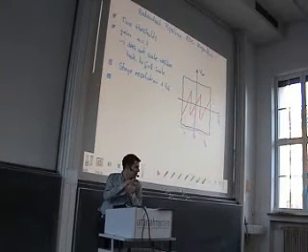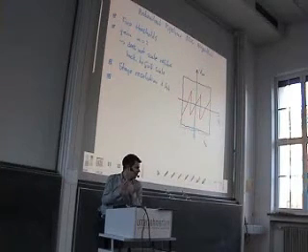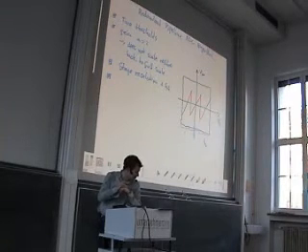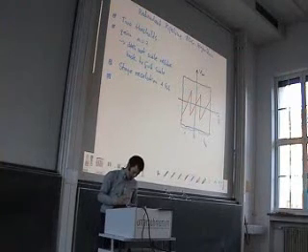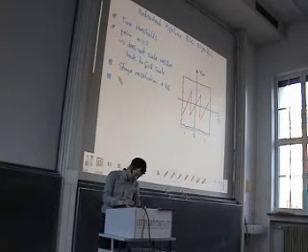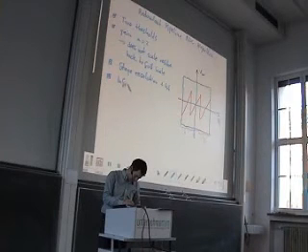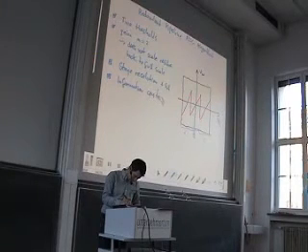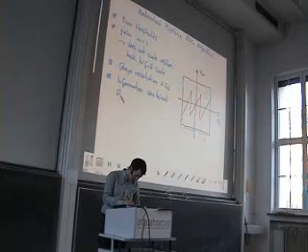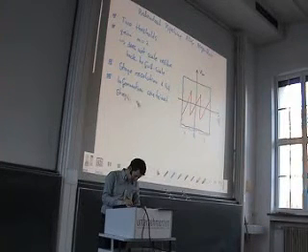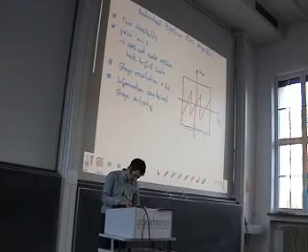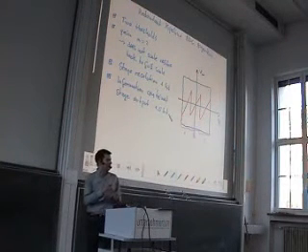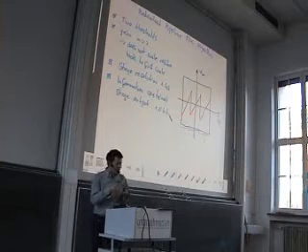This is 3 levels. It is less than 2 bits of information, which would be 4 levels. So this is somehow 1.5 bits of information here. So we have information contained in the output. And output means the output of the stage. So let's say the stage output is 1.5 bit.